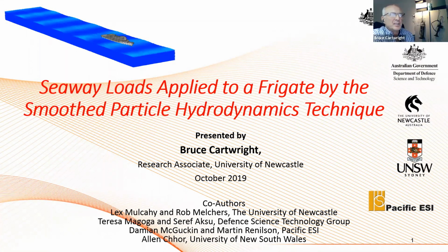Yeah, that's a good question. And there is an application that I have studied a little bit. I've looked at some of the flow through an orifice, particularly a submerged orifice between two tanks as a calibration. And yes, particle size is very important. As long as your orifice diameter is 50 or 100 times bigger than your particles, then you're probably going to be doing all right. But the other thing I did notice was that edge sharpness was a big thing. So the feature size relative to the particle becomes important then.